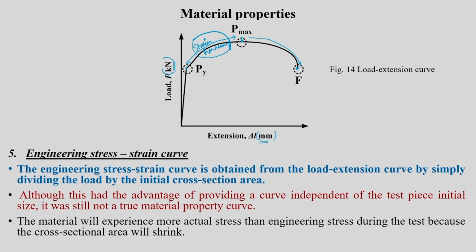Okay. So, diffuse necking means what? This is a gauge region, and the gauge region will have some sort of necking like this, over a larger gauge length. You can imagine this is the gauge length, let us say. You can imagine that this kind of neck will be formed. Neck means the area of cross-section is going to be less here as compared to the other regions. That indicates that the material's ductility is almost over. So, we have to be careful.